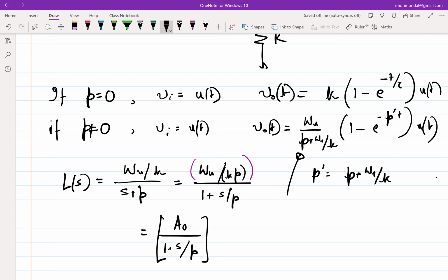Okay, so any questions? Sir, yes. I have one doubt on the feedback block diagram. The response of this total negative feedback is a low pass filter, right? K times. So if we simply put in a low pass filter, say an RC filter, will it work? What do you mean, will it work? It's a low pass filter, yes. But the loop gain should be very, very high. That's a good question.